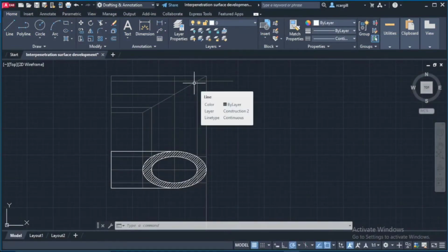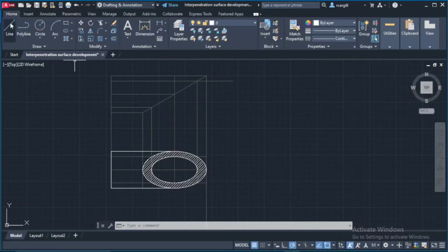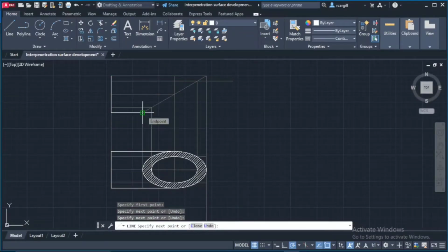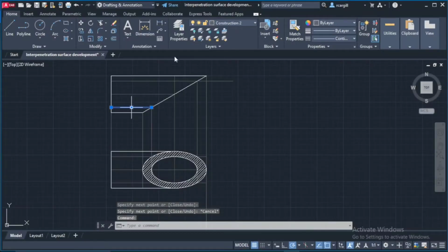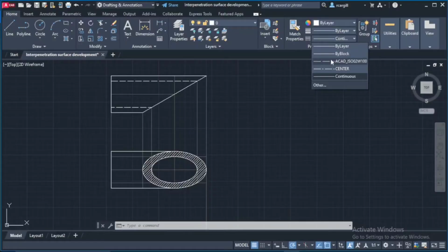Yeah. So we have the front view here. We just need to do some brightening. So we would brighten this here, make that a white line, make this a white line also. There we go. Now we would have some hidden details for here and for here. Let me just bring this back to this point here. So these lines would actually be, let me make these white lines, and also let me change this to a broken line right here, like that.